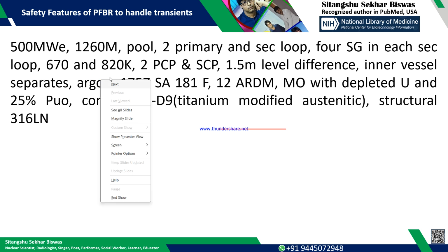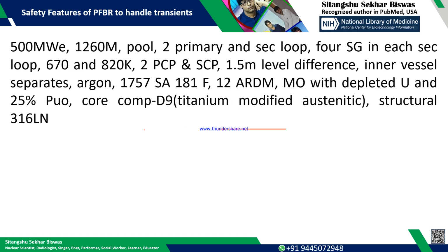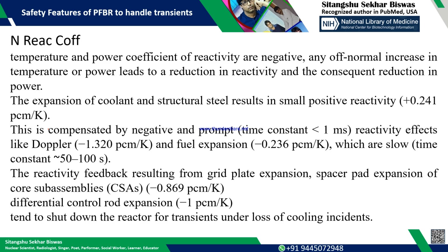The core components in the sodium pool are of D9 material, a titanium modified austenitic steel, and the other structures are of SS316LN.